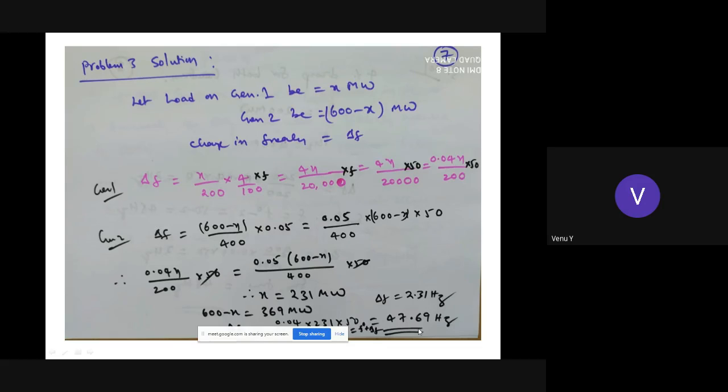That is the variation when they have equal droops. The frequency is higher compared to the previous case. Therefore, synchronization of generators with equal droops is a better choice than unequal droops.